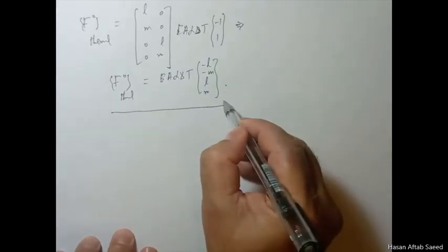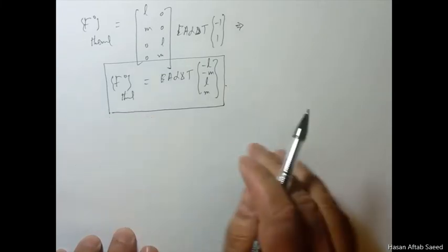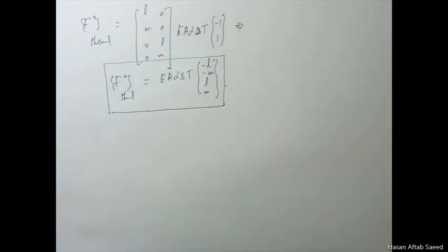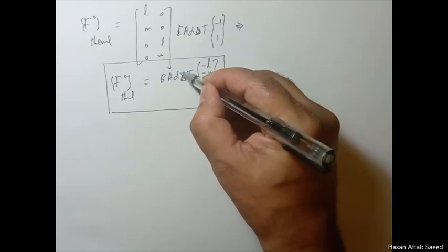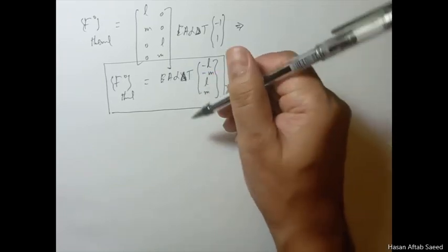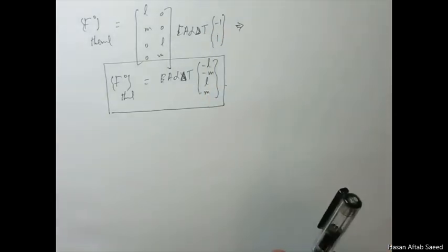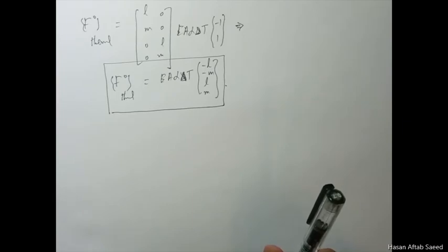This is how you deal with the thermal force vector, and this is the only vector you are going to deal with as far as force is concerned, because the concentrated force vectors are very easy to apply. You don't need to have an equation for them. You just apply them as and where they occur. As far as body force and pressure forces are concerned, they are not relevant for this kind of a problem.